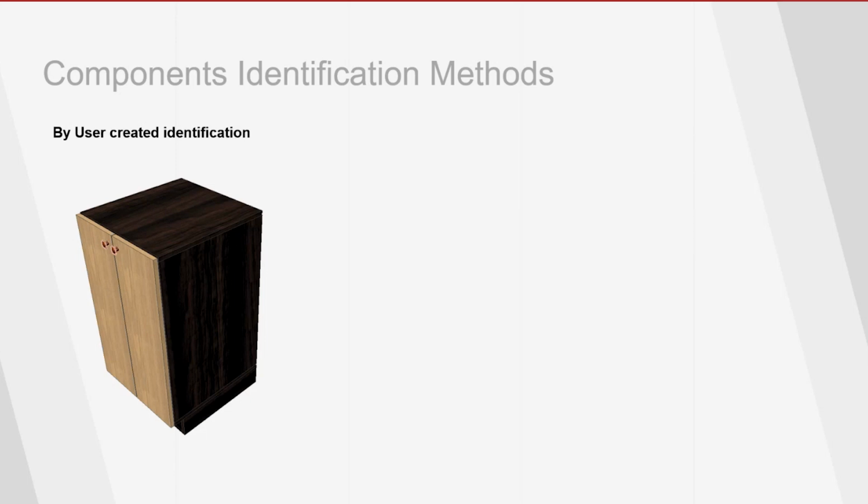Next, something important about identification methods. Now let's talk about how to identify the necessary parts to assign materials to the desired model. Somehow you need to mark them inside the model. First of all, if we're talking about fill material, you remember that we can apply it to the part component. The program needs to somehow know which material should be assigned to which part according to its functionality inside the furniture. In the given example with the cabinet, the parts are divided into facade components and carcass parts.